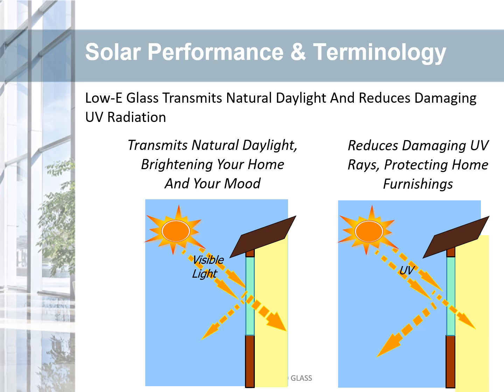Low E glass is designed to allow daylight to be transmitted into the building at a specified amount or percent transmission known as visible light transmission. Low E glass also blocks a certain percentage of UV transmission, which can be damaging to furnishings and interior surfaces. UV contributes to 50% of fading along with visible light and heat.